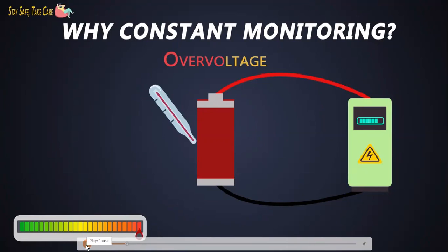Every battery has a specific range of temperature in which the battery works fine. So when the temperature increases, it ends up reducing the state of charge. This condition also increases the internal resistance of the battery and eventually the power loss across the battery increases.